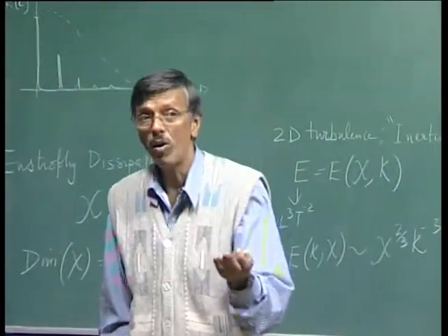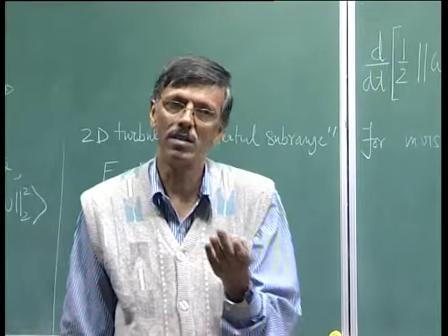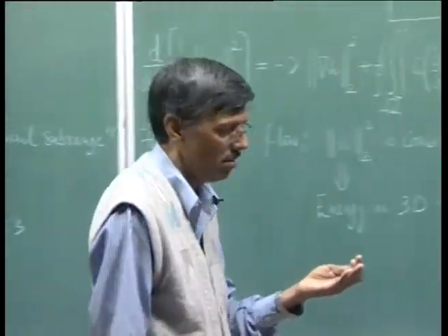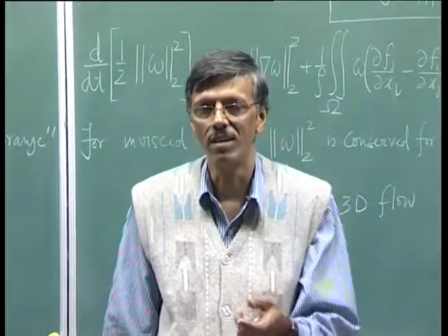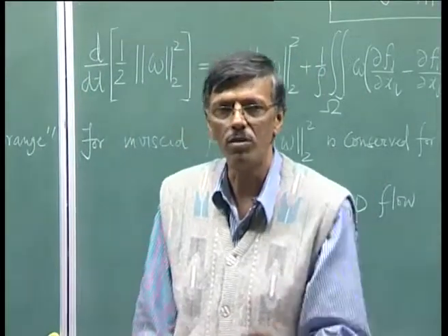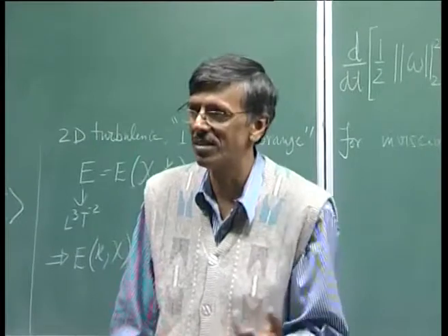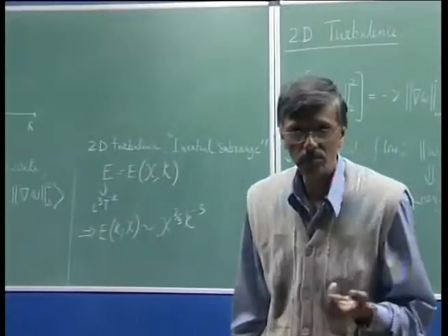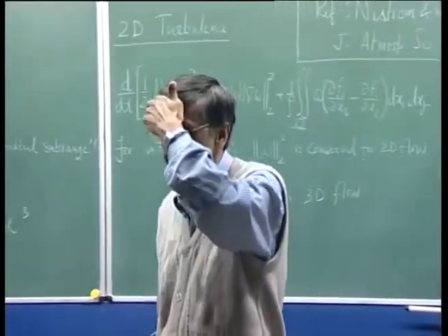In fact, any velocity profile which displays an inflection point is going to be very violently unstable. For example, for a jet or mixing layer, the critical Reynolds numbers are less than 100, even something like 3 or 4, in that range you can find those flows to be unstable. Well, the question is whether at those Reynolds numbers it is right to consider the flow to be parallel or not; that is a different issue altogether. Okay. So, any other questions? Anybody having any particular question to Piyush?